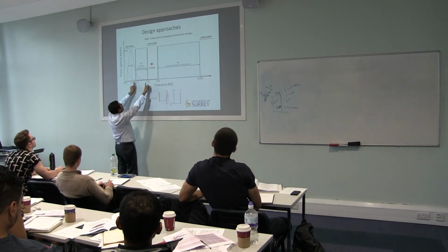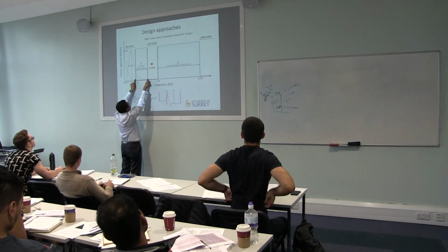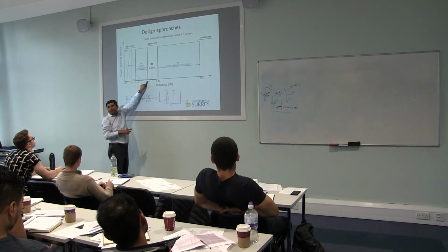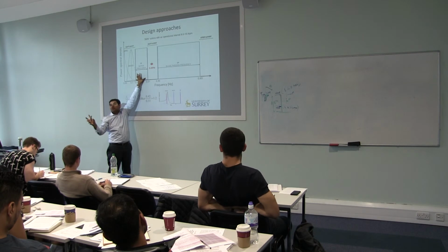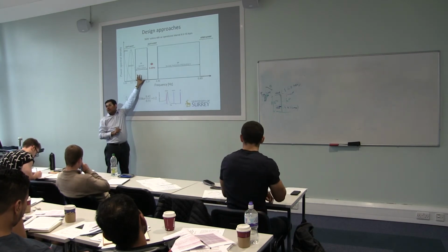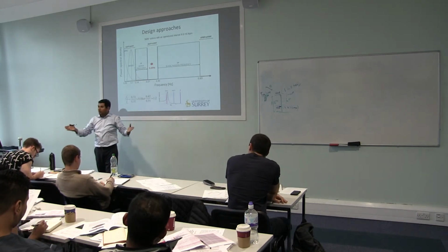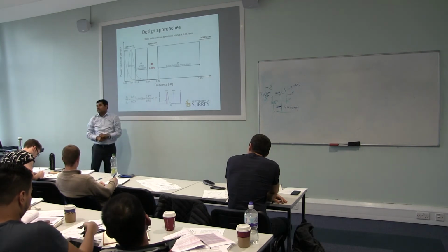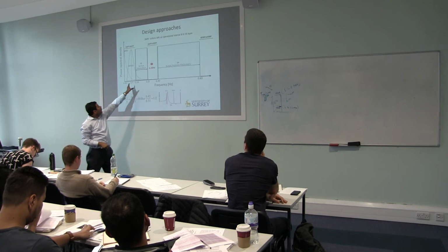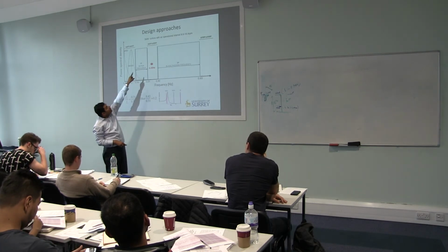This part, 1P frequency, that is the cut-in to rated range. This is a function of your choice of turbine. If you put an 8 megawatt turbine, this would be different from a 3 megawatt turbine. So this 1P is for a 3 megawatt turbine.